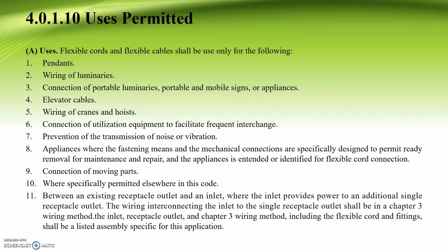Number 8, appliances where the fastening means and the mechanical connection are specifically designed to permit ready removal for maintenance and repair, and the appliance is intended or identified for flexible cord connection. Number 9, connection of moving parts. Number 10, where specifically permitted elsewhere in this code.